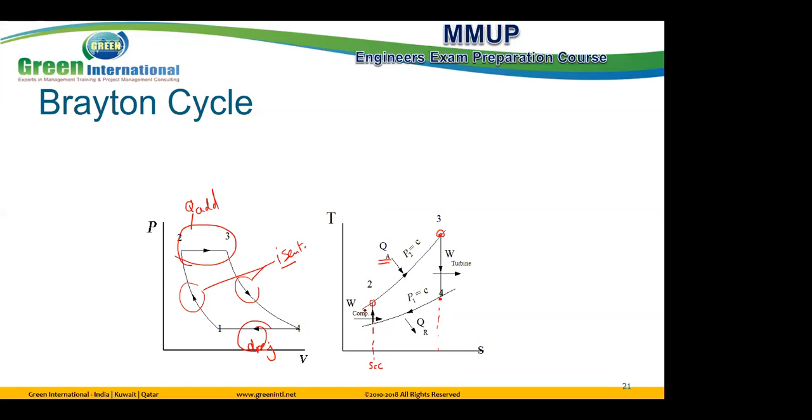See with me this important point here for the TS diagram. The curves are of constant pressure. This P constant 1 is for the heat rejected. This P constant 2 is for Q added. You see the same constant pressure lines are close together here at low temperature and low entropy, and when you go right, this range increases.